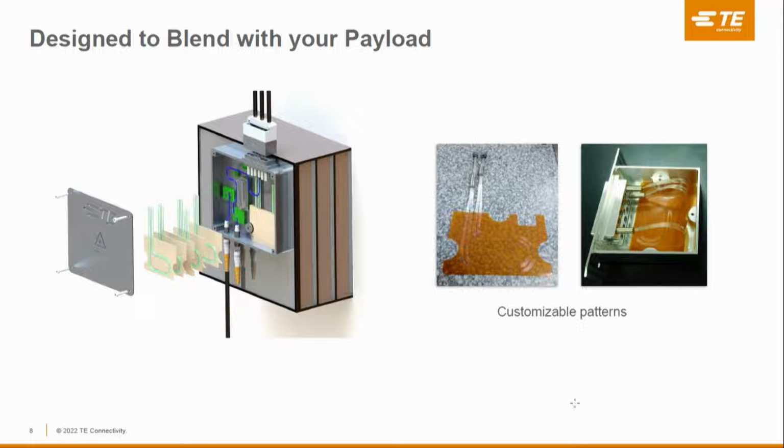The example you have there is a fully passive system where you can achieve interconnectivity, cross-connectivity within your fiber, shuffling your signal, having one fiber coming in on the same termini but going into a completely different output where you want that signal to be within your system. But also some of these legs, which are the little parts coming out of the orange area, are kept on, for example, for space compatibility here.